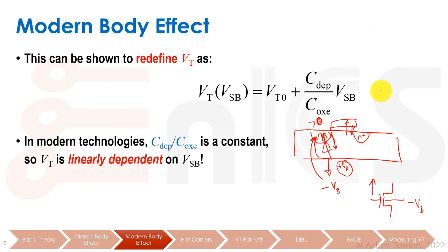In general, what we want from a transistor: traditionally we have our transistor, we have our gate oxide over here, and there's the gate. We can call this C for channel, that's the voltage we have over here, and this we'll call B, for body. What we want to do is change the channel voltage by 2 Fermi energies in order to cause inversion on the channel, and we do that by applying voltage to the gate. So we want some transfer function of voltage from the gate to the channel. There is a capacitor here, an electrode, a dielectric and another electrode.